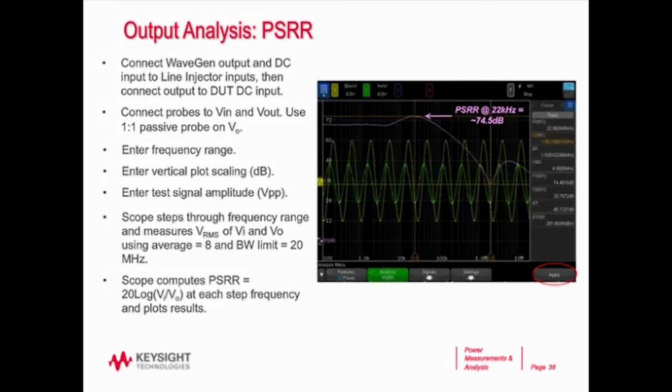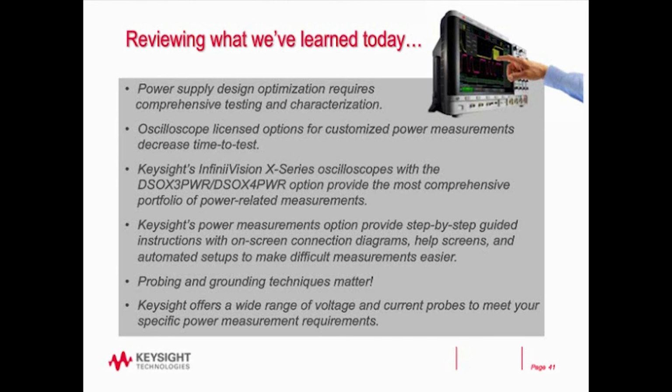But I would say the maximum dynamic range is about 70 dB. So the bottom line, this is what I've been calling a poor man's vector network analyzer. This doesn't replace a network analyzer. A network analyzer would do a far better job, has much more dynamic range than an oscilloscope. But if this is good enough for you, it's a pretty simple and inexpensive solution.